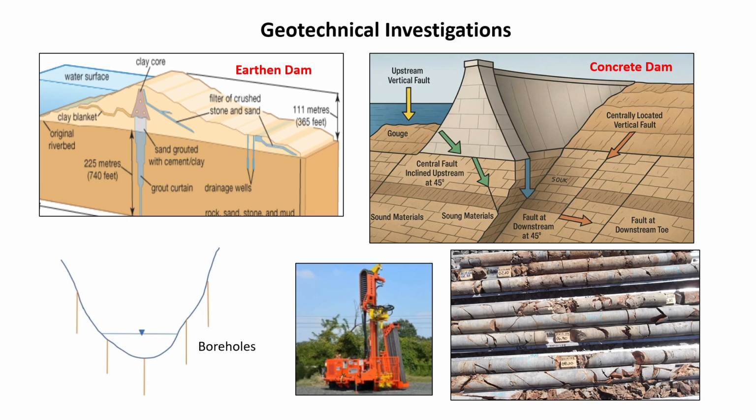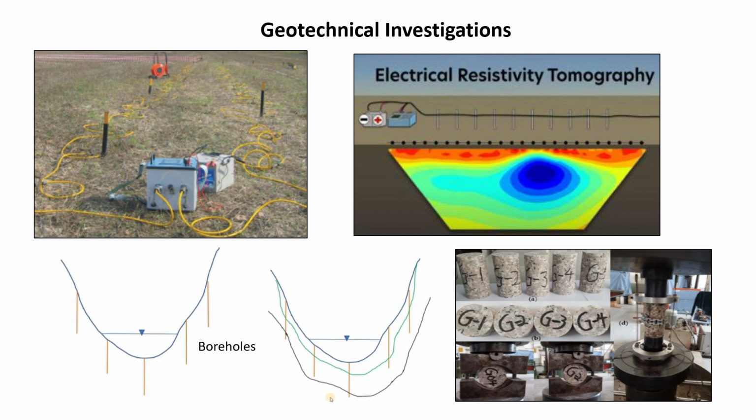For concrete dams, to stop the seepage, we have to grout up to sufficient depth to stop the seepage beneath the foundation. We have seen about boreholes. There are other techniques which gives fast and accurate data with limited applications. These are called geophysical investigations. There are several methods such electrical resistivity test, seismic refraction test and others.